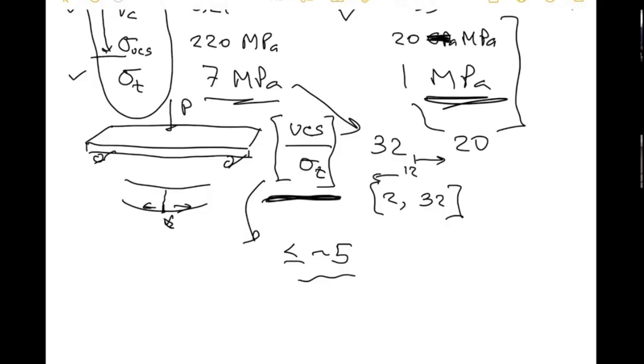Another correlation people know is that if they look at the modulus of rock, the higher the modulus, typically the higher the strength. Stuff that's really, really stiff is often stronger in compression.